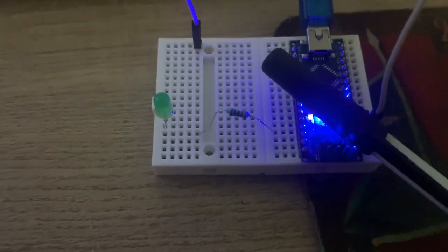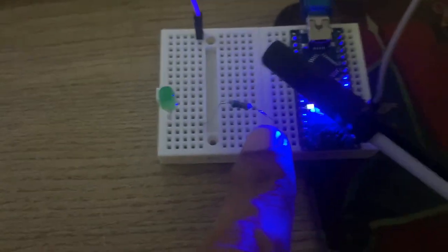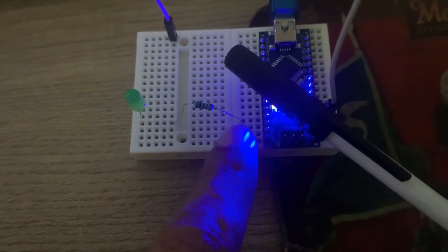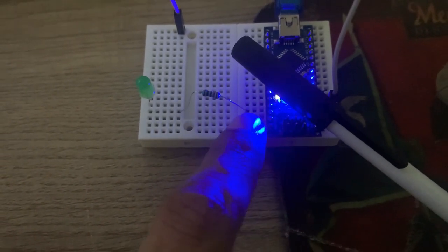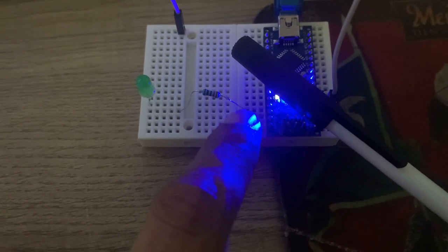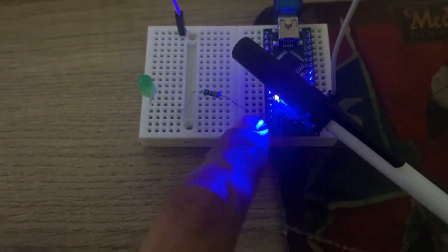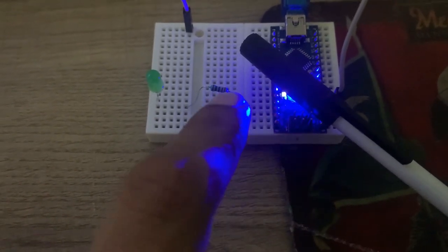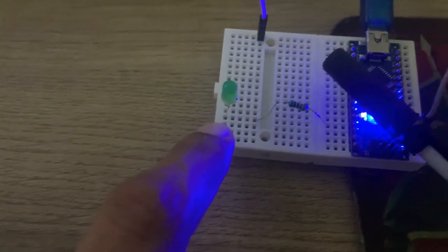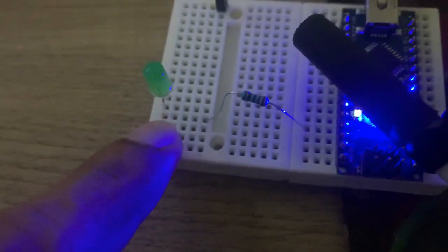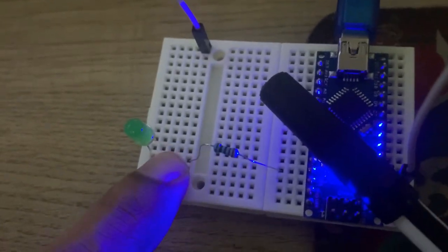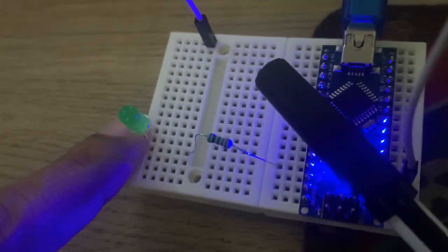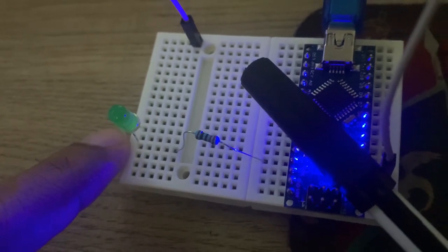But anyway, as you can see, we have right here our 5-volt pin, our resistor connected to that 5-volt pin through the breadboard. Those 3 dots, they're all connected. We have that power jumping over, going into the positive end of the LED. And then behind that, if you guys can see right there, is where we're going to ground it.